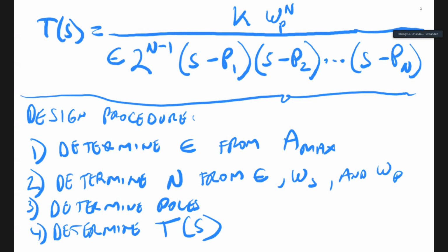And again, this is called the realization of the circuit. Those would be design equations that relate the coefficients in T of S to another T of S that has coefficients as group of component values, which would be your R's and C's, assuming that you're not using inductors.